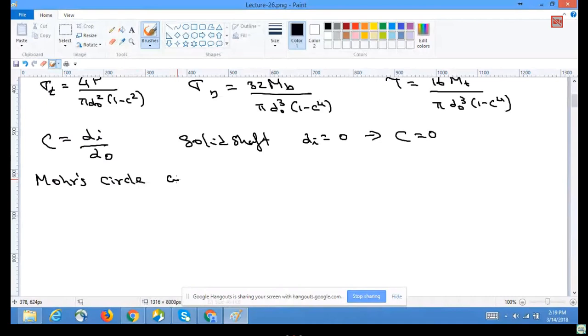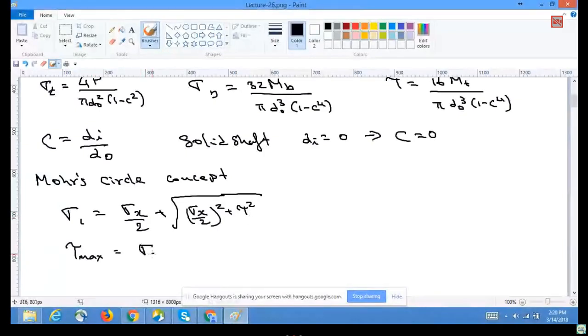we have obtained principal stress as sigma x by 2 plus or minus square root of sigma x by 2 whole square plus tau square is equals to, where sigma x is equal to sigma bending, kind of tension or compression at different layers in a different manner, and anyway the axial thing is also kind of sigma t.